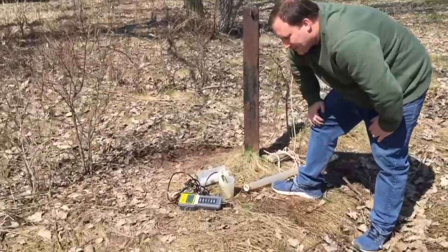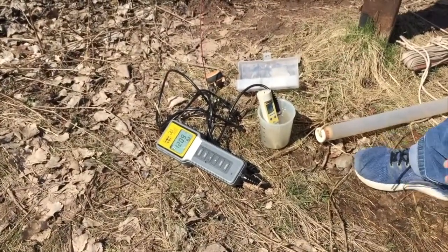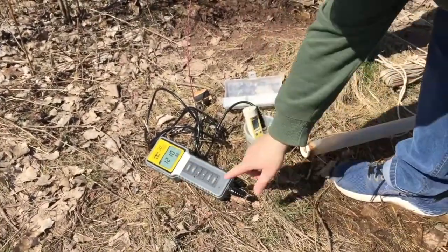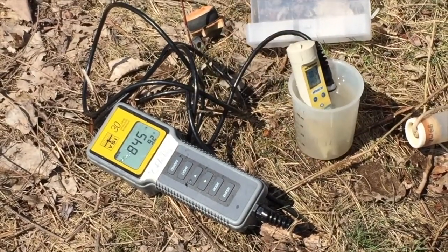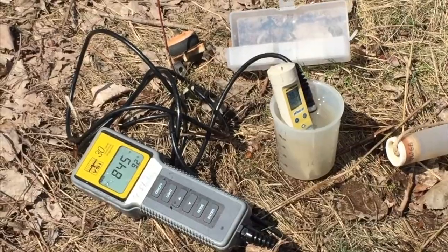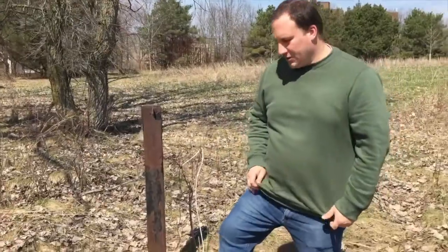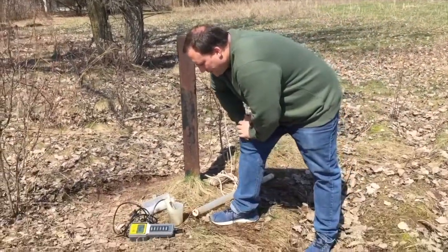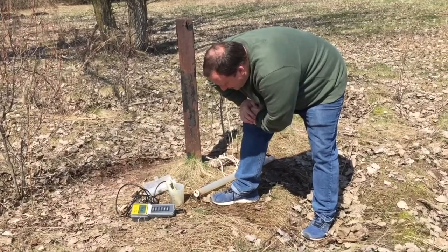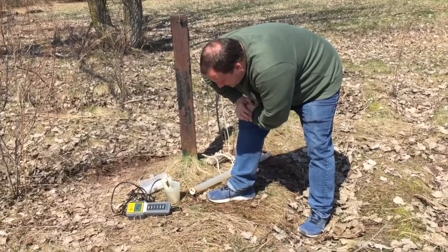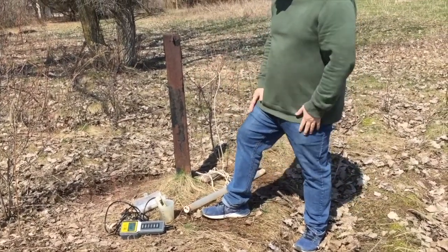1208 is the specific conductance with its flashing degrees Celsius on this meter here. That's the temperature corrected one. And if I change the mode, it's 845 microsiemens without the degree Celsius symbol flashing. That's conductivity, which varies with temperature. The other one is temperature corrected. Okay, for pH, I'm at 7.80. 7.80. So that's the best way to do this.